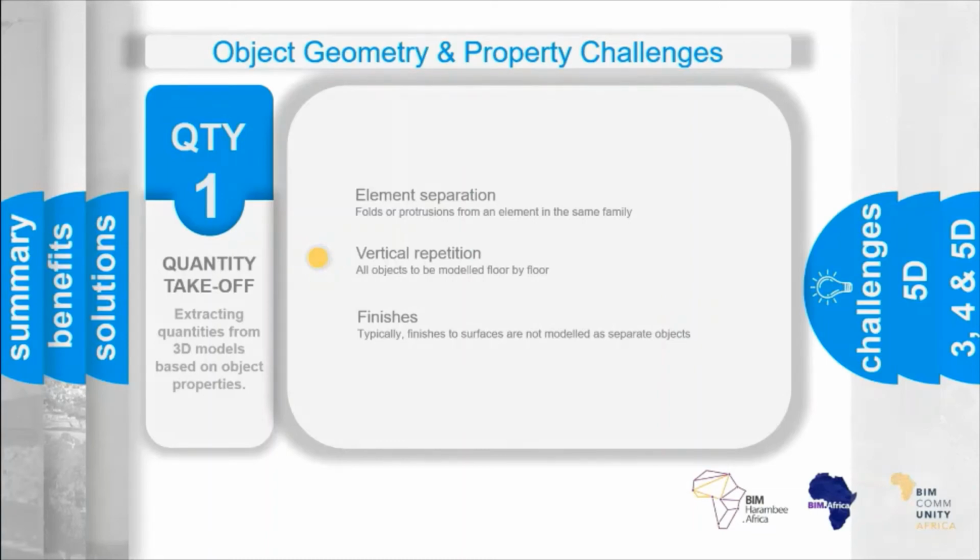It also goes down to assisting us in zoning and applying costs to different functional areas and categories of the building. If a column is modeled or a wall is modeled the entire way through a building, we're unable to split those costs, and it comes out as a single sum. So by way of example, columns and walls should be split per floor. Columns and walls also in the substructure or foundation should ideally be modeled as separate elements from the superstructure and covered also using that function to state that they're in the foundations, and that's added as a property. Likewise, external elements should be split from internal elements.